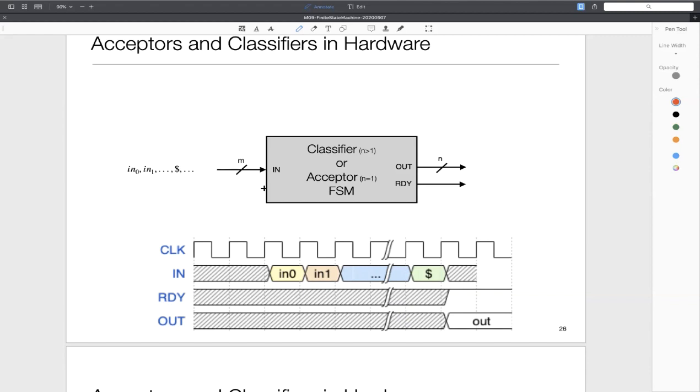What often happens is that your hardware runs very fast, on a clock of megahertz or hundreds of megahertz, and your input is coming from a keyboard. Whenever the user presses a key, it takes milliseconds at least, sometimes even more. So a single key press would actually last many, many clock ticks.